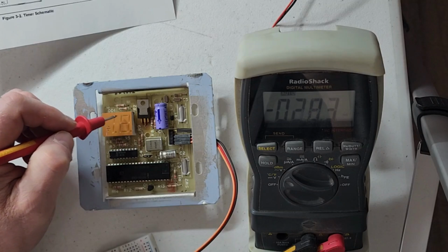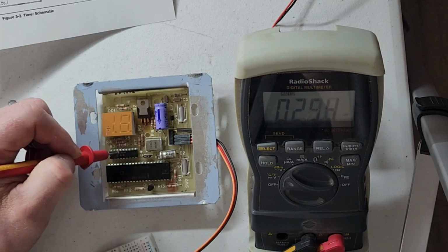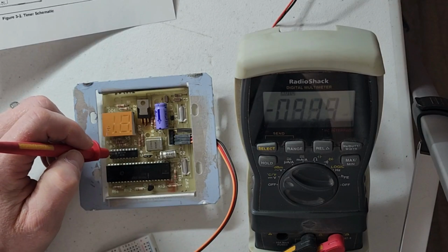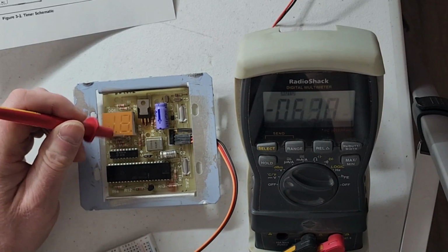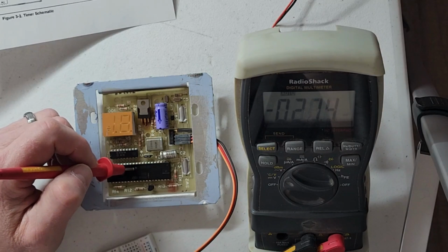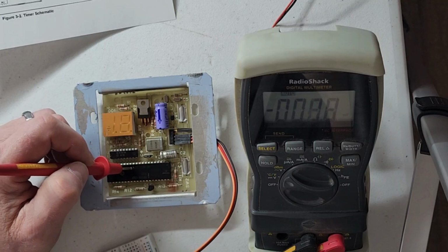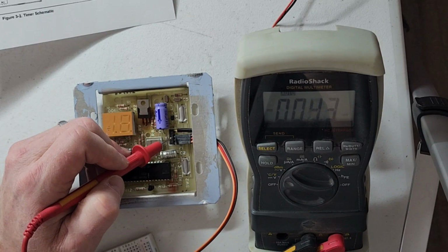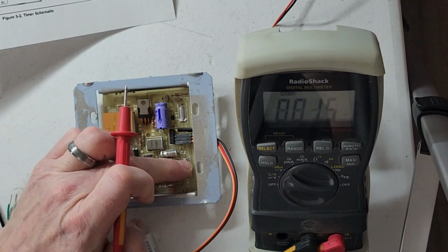This is just the display driver. We saw 1 and 8 completely lit, so obviously this buffer or whatever it is for the display seems to be working. But it's almost like the program is messed up in this chip, because when I short this, then it should give me the L.